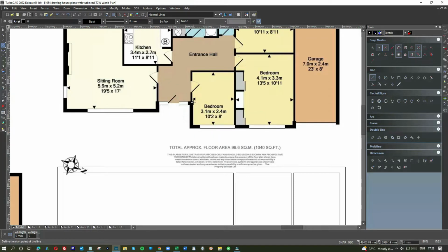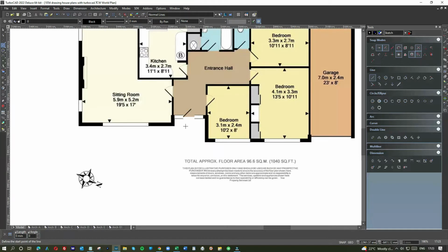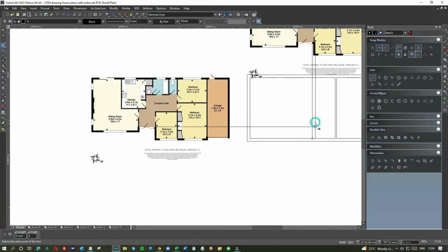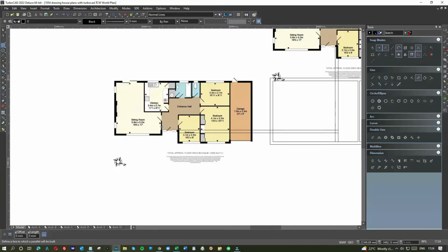Right, so what we do is we get the inside measurement there, and we know we need a parallel tool, which is going to be 330, tab minus 330. And before I do anything with this one, I'm going to use a horizontal line, and I'm going to use it from the inside. Parallel, tab minus 330. And that's going to go as far as this side here.